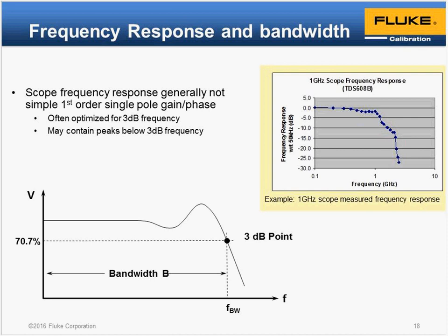But as metrologists, we'll be wanting to think about what's the uncertainty with which we can measure that bandwidth. So we've got to translate a voltage measurement into a frequency, because uncertainty in the signals that we're applying, the accuracy with which the oscilloscope calibrator produces those signals at the low frequency, at the high frequency, translate to a voltage uncertainty that then turns to a frequency uncertainty through the slope of the response at the measured 3 dB point. It would be rash to assume that's a nice well-behaved response, as you can see evidence in the measurement that I've got at the top there.